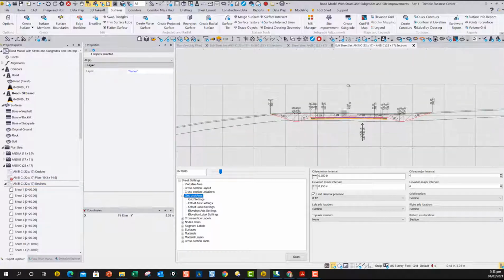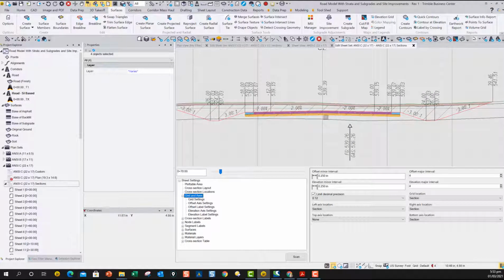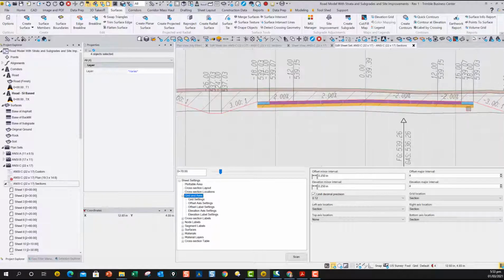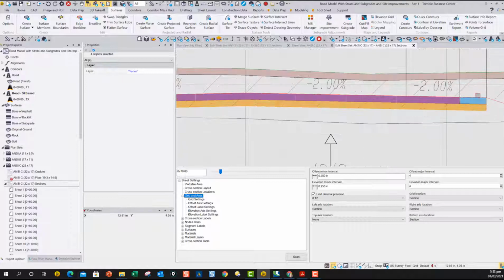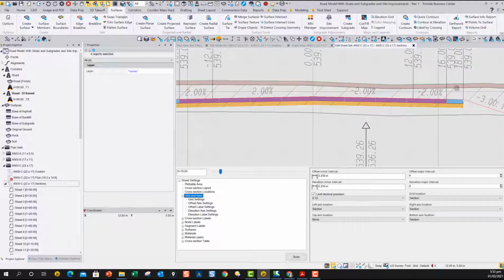I still think that the template approach is a better approach, but this works pretty well for giving you the cross sections in the large situations. Say curb and gutter, I would have to think about how you would do that for the different material stacks, because when you have an irregular shape finish grade, obviously the pavement site improvements are just being applied vertically beneath that, and when you've got a curb and gutter that's irregular in shape, you'd have to break the curb and gutter into pieces, and the sloping face you'd have to just ignore or something like that.